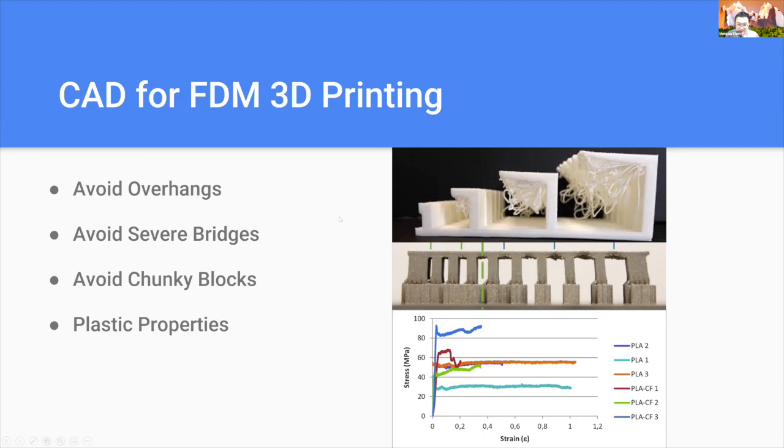Right. On the second picture here, you can see this is what we call bridging. The larger the bridge, the poorer the quality of the 3D printing. So you want to avoid very long bridges. These not only do not look good aesthetically, right, but also the structural integrity is compromised when the model isn't printed out as you designed.